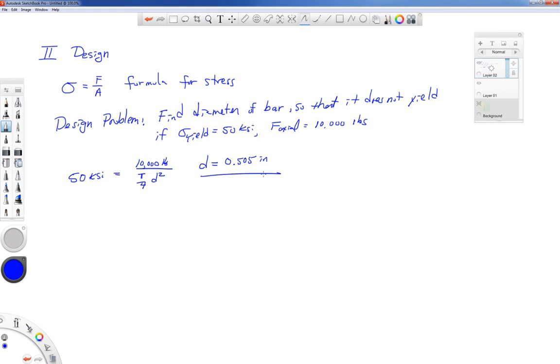Well, there's an assumption here that we've made that we may not have explicitly stated so far, and that's that the yield strength that's reported in material properties tables or by tests may be from a limited number of specimens, and it's often reported as an average value. In reality, if you were to test a bunch of specimens from the same batch of material, or different batches of materials even, you could have some variation in that yield strength.